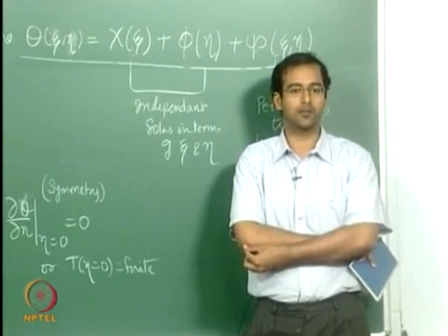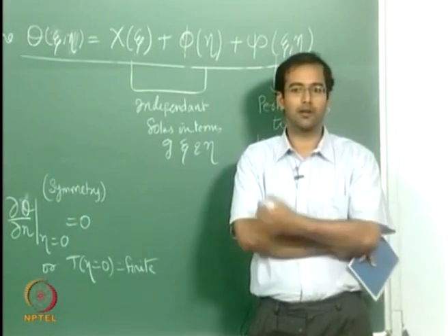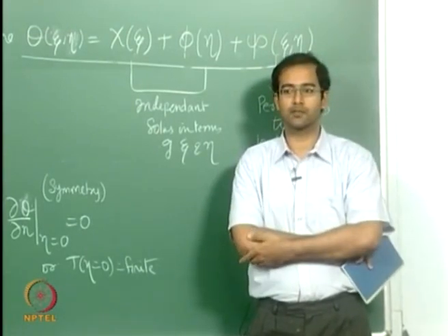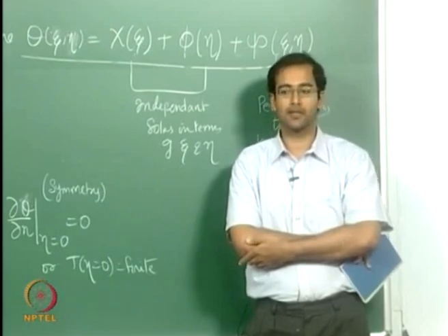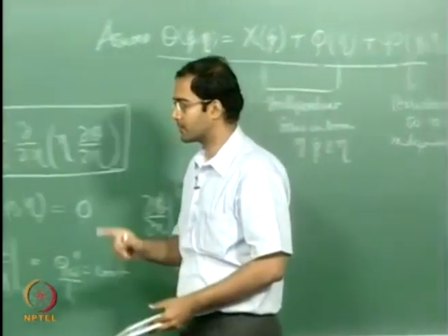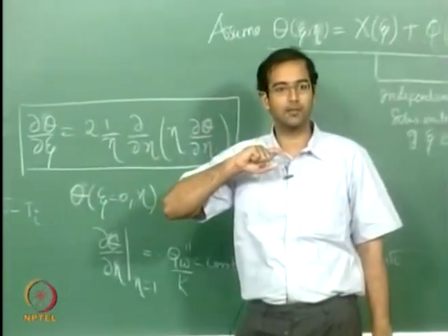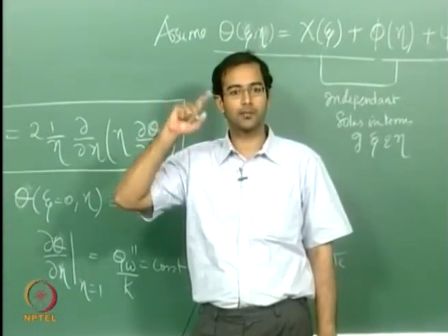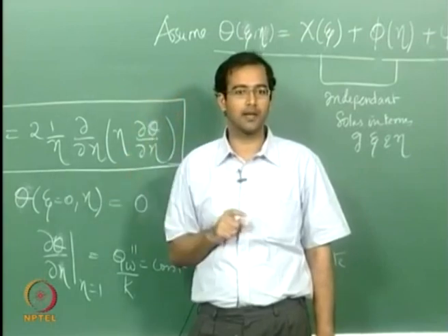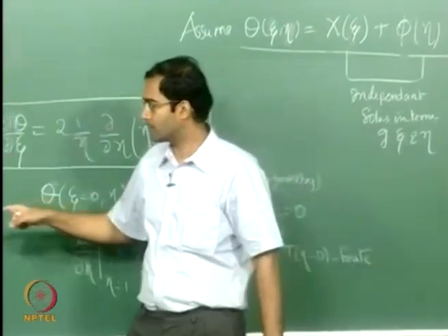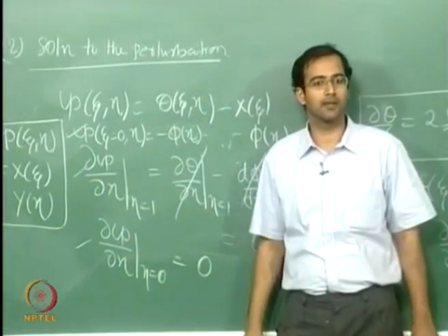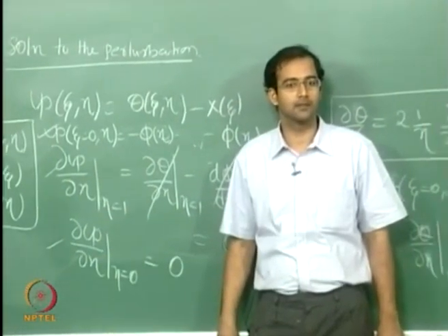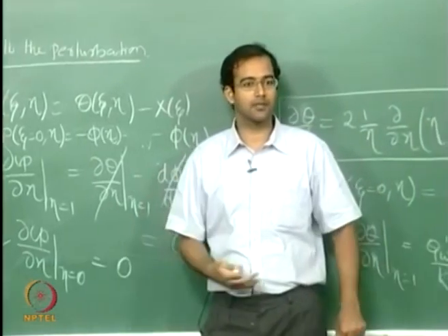It will be a Bessel equation, and you already know the solution to Bessel equations. You have to just combine the Bessel solutions, and the only difference between this and the constant wall temperature case is that there the temperature was 0 at r equal to r naught. Here you have both gradient 0 boundary conditions. Okay, so this is the difference. And after that the solution is straightforward.